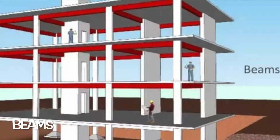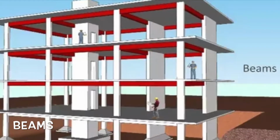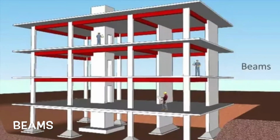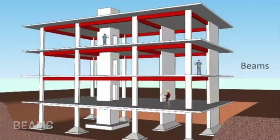Columns are vertical structural members that transfer the vertical loads to the foundation through the footings by compression, most commonly used in the outer frame or shell of the structure, but can be used inside the structure depending on the size and type. Beams are horizontal structural members between columns. They are used to support loads and transfer them across their length to the columns, which are then transferred into the building's footings and then the foundation. They are also used to carry the moment or rotational force of the structure.